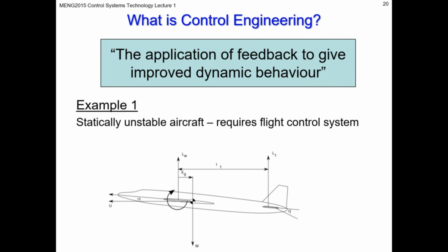And some of the systems we gave as examples from our household systems are actually also open loop. Like, say, a basic washing machine would have a cycle which is programmed. So the cycle would remain constant regardless of how many clothes are in the washing machine or whether water goes in or if there's no water. It would just proceed through its cycle because it's designed to just be triggered by time. So that would be an open loop type system, and I think active aero would probably be open loop as well. Now let's look at some closed loop systems.